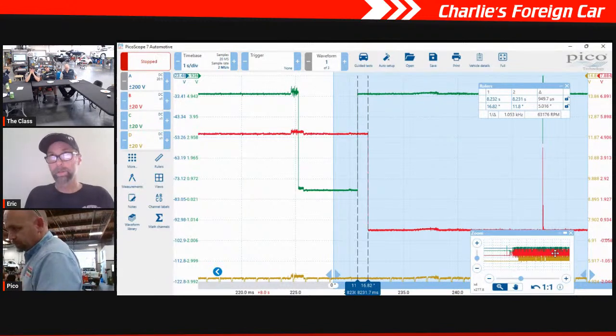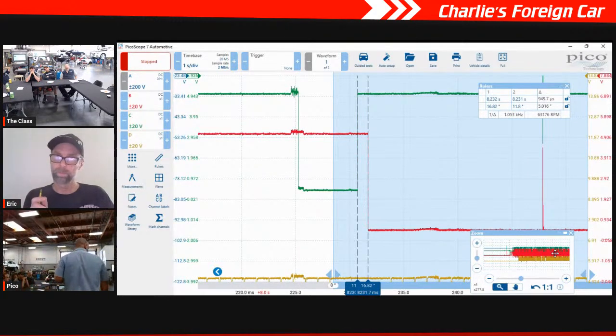So when the intake is activated, that gap shortens up. So it advances the intake cam. Is that correct? When the intake is activated, the time gets less to the crankshaft, so it'd be closer. Yeah, so it'd be advancing, right?